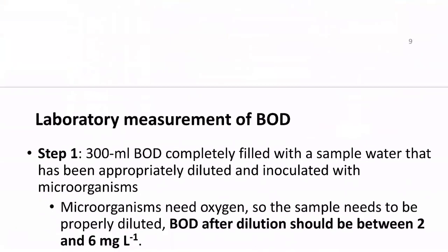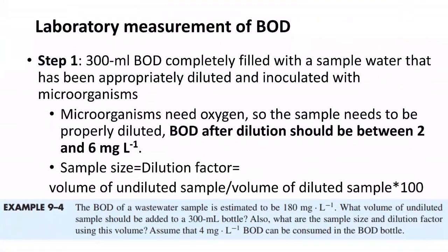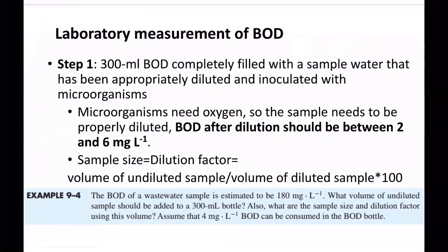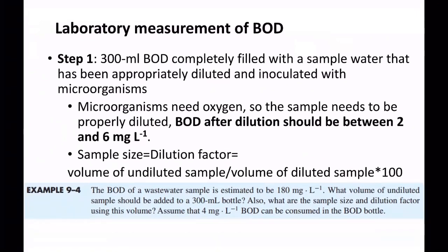So we talked quite a lot about the theoretical BOD and how it depends on time and temperature, but we haven't really talked about how we measure it, right? As we discussed earlier, it is quite straightforward. We just measure the dissolved oxygen, okay? We have a probe that can measure the oxygen concentration in the bottle, and then we just measure it at different times, right? But there are some processes that make it a little more complex.